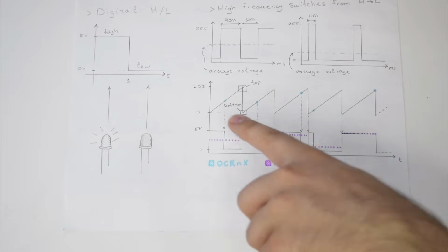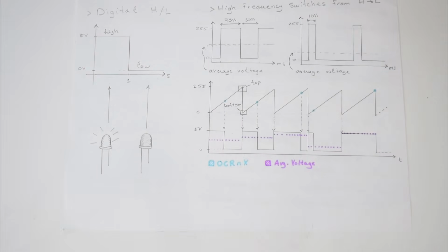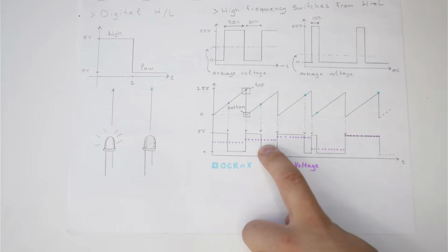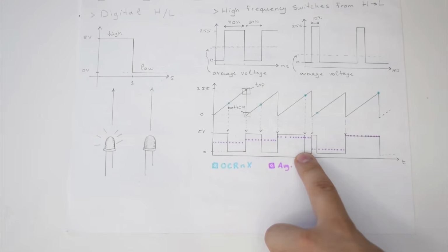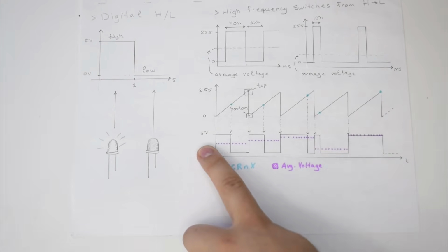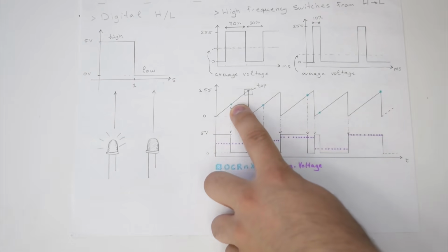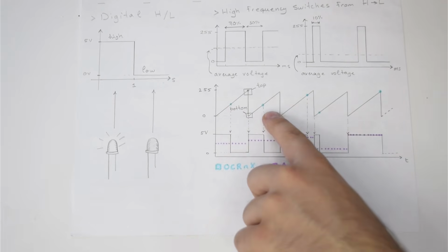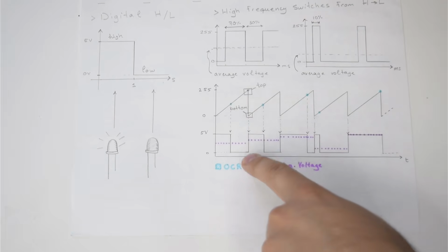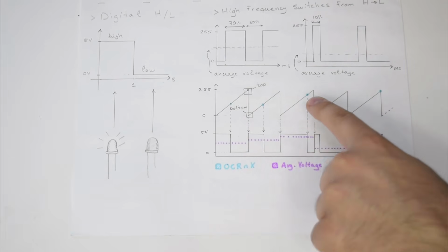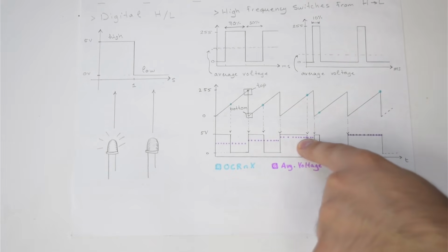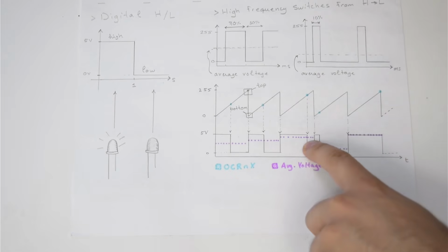So this is the timing diagram of Fast PWM on the Arduino. I've also made lines covering the average voltage, made by putting some purple dots. Here, since the flag is around halfway, the voltage will also be around half. Here it's slightly more than half, so I made the dots a bit higher than half. Here it's much higher, so it's almost full brightness, somewhere around 4.8 volts, and it goes back down.